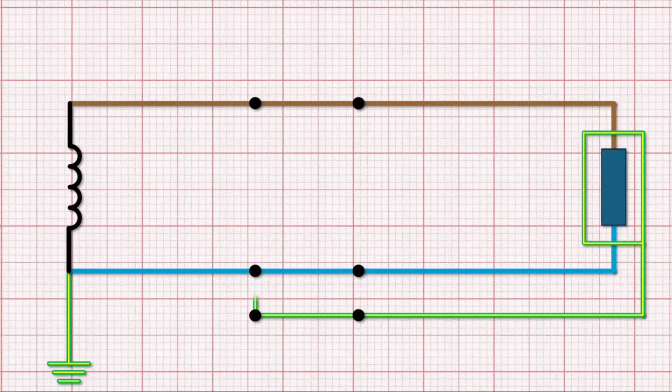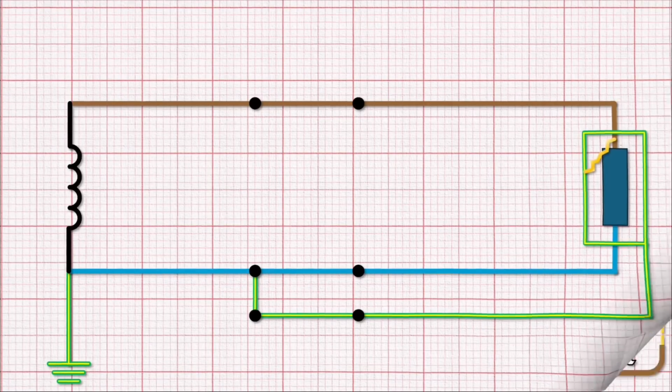The other fault of negligible impedance that we come across is earth fault, as its name suggests. This is what occurs when the line and earthing system come into contact with each other. This can occur when a line touches a circuit protective conductor, or if a line conductor touches an exposed conductive part. Either way, this creates a similar issue to a short circuit. The opposition to current flow becomes extremely low, and therefore the current will be extremely high.